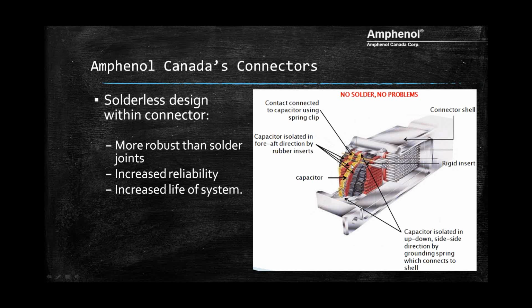Keeping in mind that these ceramic capacitors are very brittle and can crack quite easily, it's protected for you in the Amphenol Canada system. We also, in order to ground to the shell, have the ground spring which connects the capacitor to the shell, and that gives you the up, down, and crossways stress isolation through the insert here.